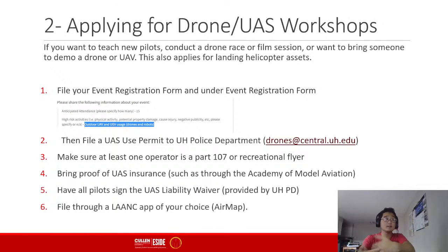And then day of, when you're ready to fly your drone and everything's set up, file through LAANC, or the app of your choice. Bear in mind, this is a process, which is why we're telling you to file. If you're doing a drone event, you should file 30 days in advance of your test date so that you know. You should also be smart. You can file for multiple days in the same event. So if you're going to file for a day and it's bad weather, file for 2 or 3 days so that you have some wiggle room to be ready for that.